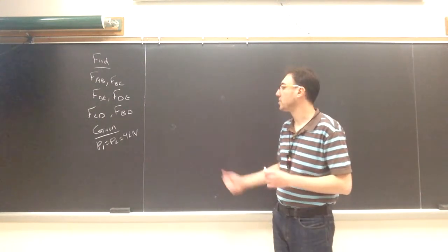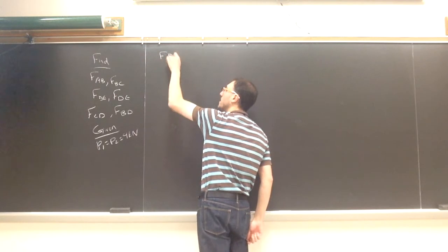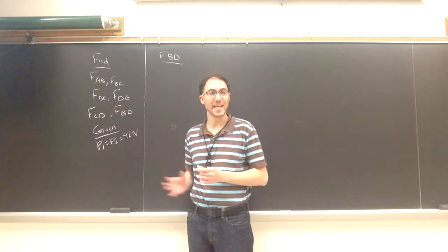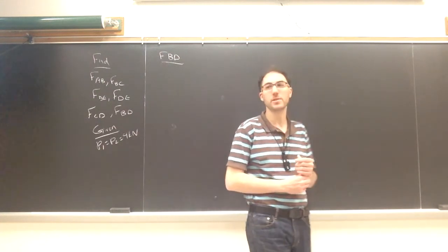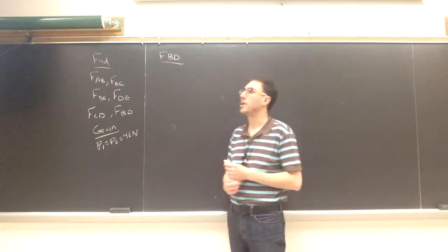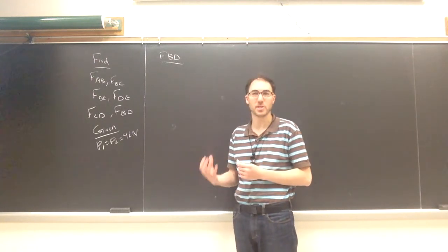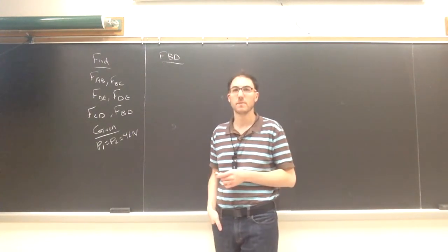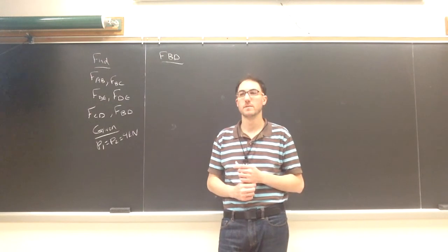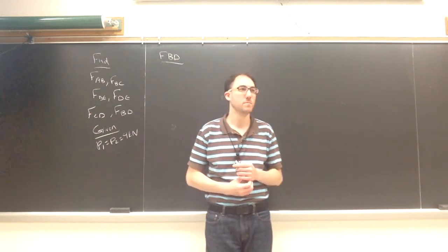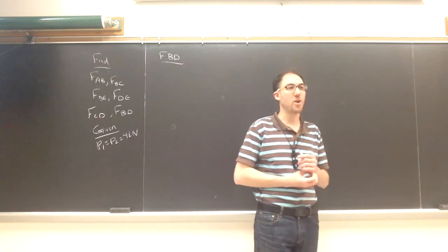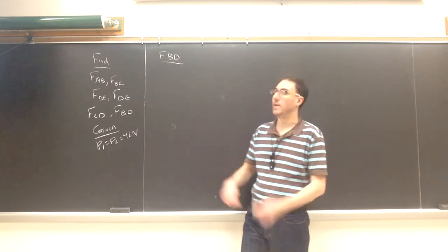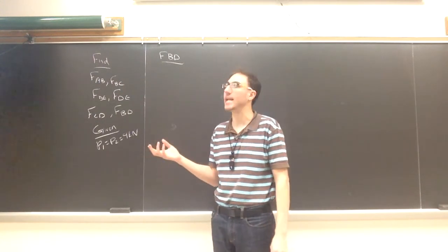So before we get to a strategy to decide what's the first free body diagram that we draw, we want to see, is our system statically indeterminate or statically determinate? Looking at how this is arranged and how it's attached to its supports, is this going to be a statically indeterminate or determinate structure? Right? Indeterminate, and why is it going to be indeterminate?